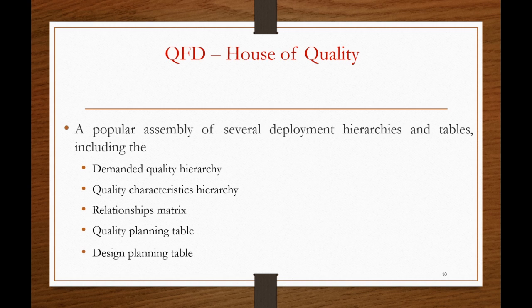The level 2 QFD matrix is used during the design development phase. Using the level 2 QFD, the team can discover which of the assemblies, systems, subsystems, and components have the most impact on meeting the product design requirements and identify key design characteristics.